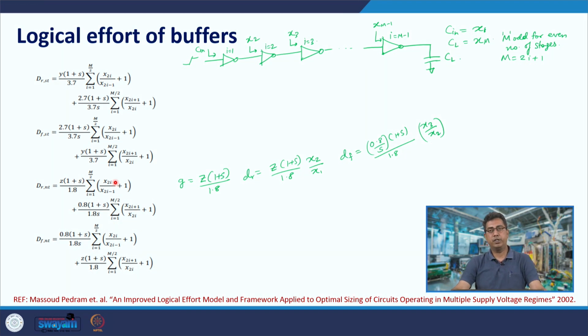So, in this lecture we have discussed the back of the envelope calculation for estimation of the logical effort values for inverters using asymmetric gate sizing, and also discussed inverter chain delays and how to optimize inverter chains using this modified method of logical effort for asymmetric gate sizes.